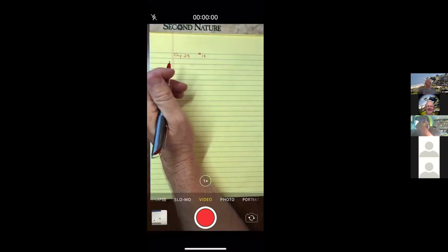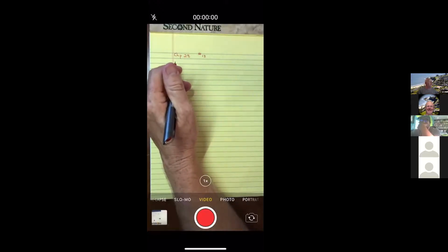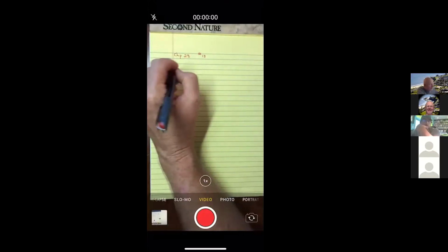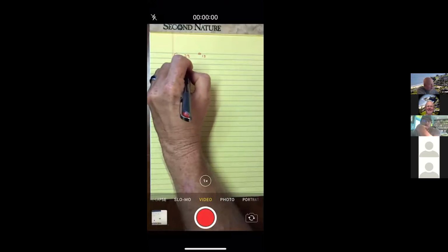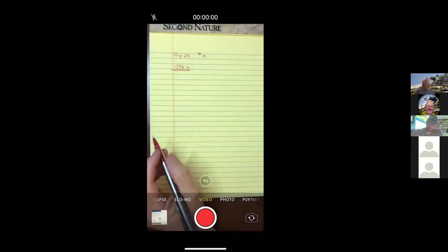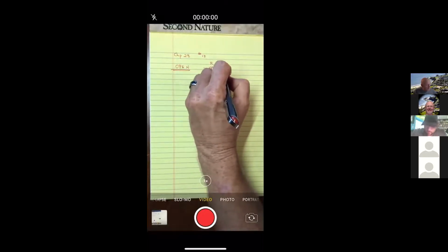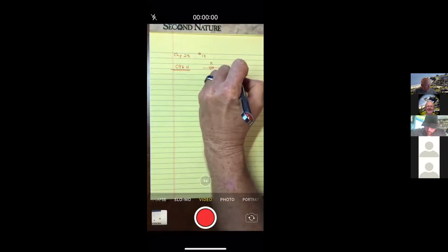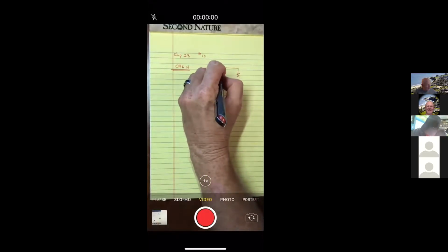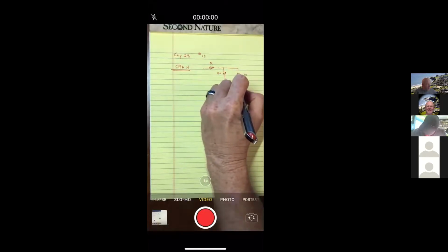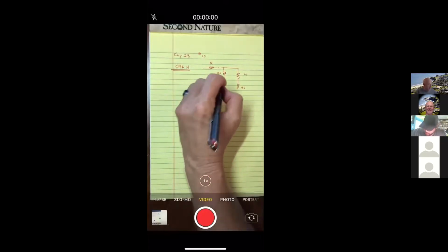With some experience, you would be able to say in the open position, there's a lot of resistance, and in the closed position, there's a little bit of resistance. But I'm not even going to go there. I'm just going to work out the math here. Let's look at when the switch is open, and that's the picture that they have. It would look something like this: you would have this unknown resistor R that would then branch out where there is a 90 and a 10. And then because the switch is open, I won't even draw the switch in my circuit diagram.